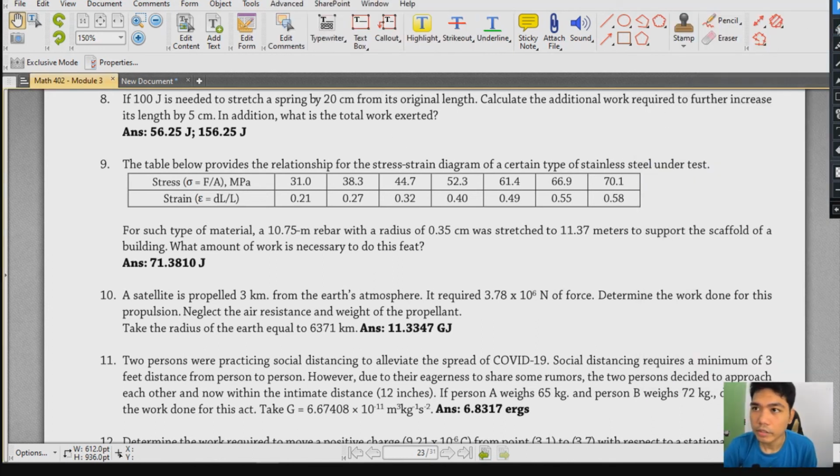So the value is, in the regression, that's the B, 103.7412. Okay, so what I did is letter E, because that's often the representation for the Young's modulus of elasticity. So we call that the Young's modulus of elasticity. That is the slope of the ratio of the stress-strain. So that's what we're going to use.